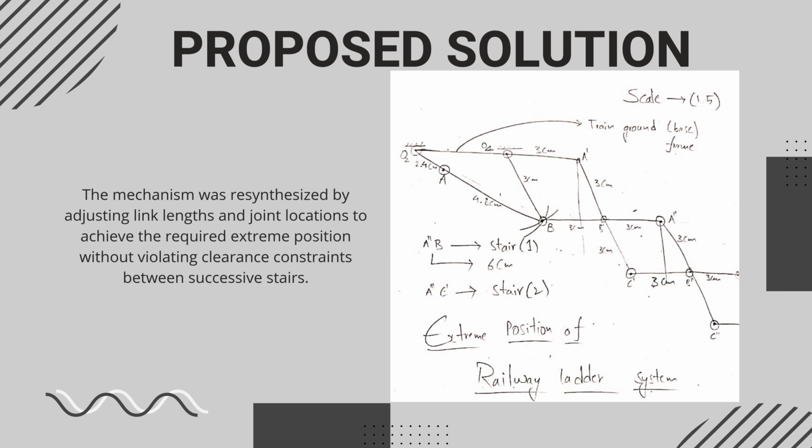Solution. To address this problem, we refined the mechanism geometry, adjusting pivot positions and link dimensions so that no overlap occurred at any point of the motion. This refinement ensured a smooth and safe transition between the configurations.